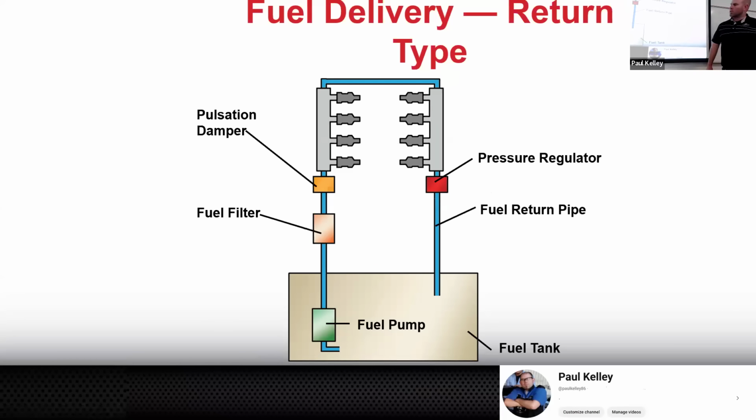So it was good that they put the fuel pump in the tank, because the fuel pump doesn't want to do a lot of suction, but it's also like, hey, pump as hard as you can all day long. That fuel pump's had a hard life. So this was old school. If you hear the return style fuel system, this is it, right? You'll see the next design's a little more modern.